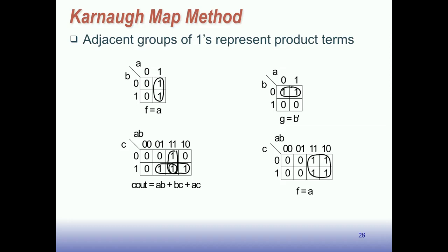So the technique we have is you fill in the table as if it were a truth table. And then you look for these groupings, because the groupings tell us how to look at when the variables change and which ones we can eliminate and which ones we don't. For instance, here, if we were to put this function in here and we don't know what it is, we can see here, oh, when we move through all the values of the onset, A stays constant at a 1, B is variable, so therefore the function can't depend on B, and B is not part of the result. So it's kind of what I showed you in the truth table, and we can do it in 2 dimensions. So here's the technique.